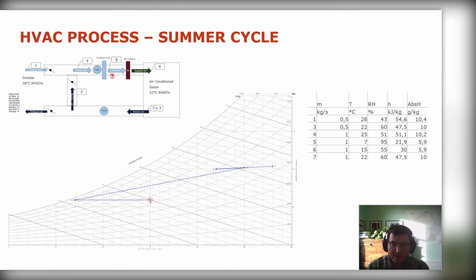And then I'm going to be cooling it. It will go through a cooling coil. Now, that's a very interesting process. The way I've shown it here is like that, but how do I know and why does it go like that? You have to think about what's going on. Your air and moisture mixture is going through the cooling coils. And as it goes past the cooling coils, which are colder than the air itself, otherwise you wouldn't have the heat exchange, the cooling liquid, that could be refrigerant in the DX coil or water inside the chilled water system, is absorbing heat out of the air. So the cooling coil is heating up, the air is cooling down.